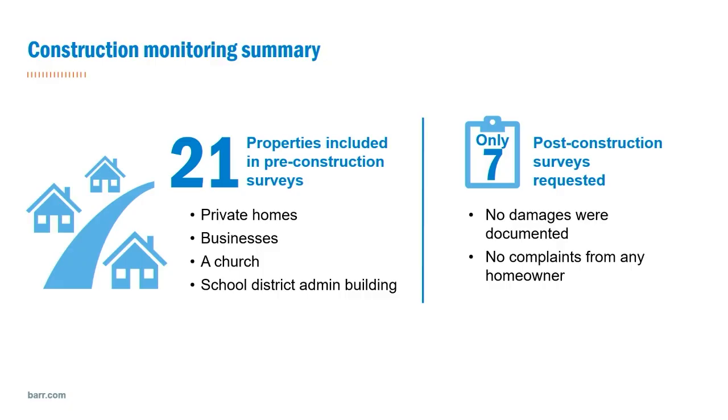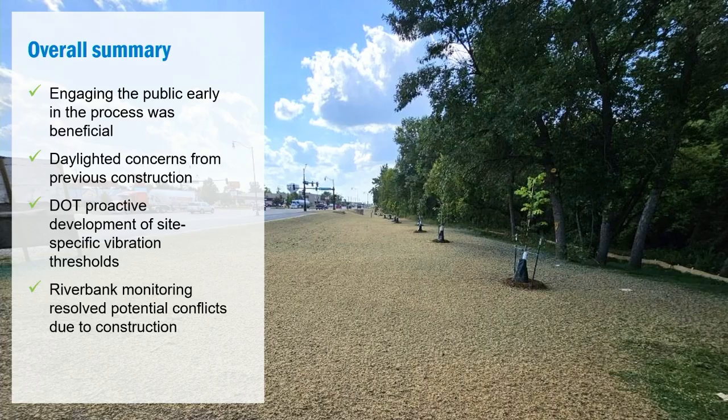As part of the construction monitoring summary, we ended up doing 21 pre-construction surveys at properties. They range from private homes to businesses, a church, a school district administration building, and only 7 of those asked for post-construction surveys, so I would call that a success. No damages were documented, and we really didn't have any complaints from any of the adjacent homeowners.